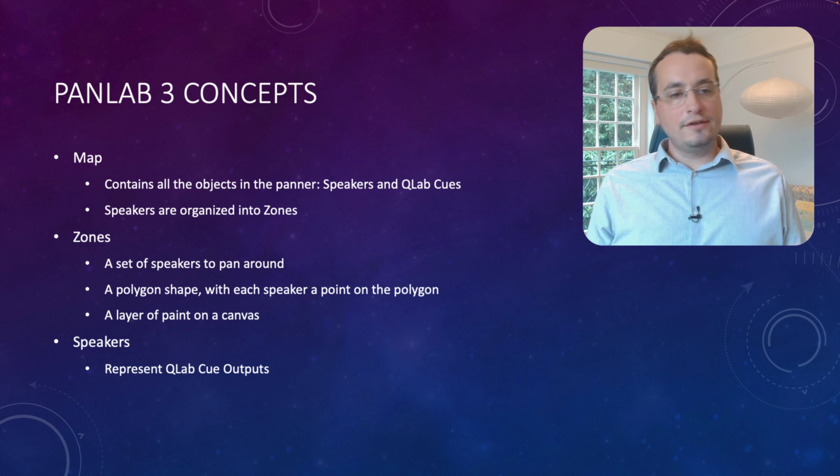Essentially, you can see a couple of things going on. We've got this visualization that I've left up so you can see what's happening. You can see that the auditorium zone extends over the stage zone. The influence of it extends onto the stage. If I adjust the size of the zone boundary, the size of that influence out onto the stage decreases. I can do the same thing for my stage zone, make that a little bit smaller, and you can see I've got this overlap between these 2 zones.